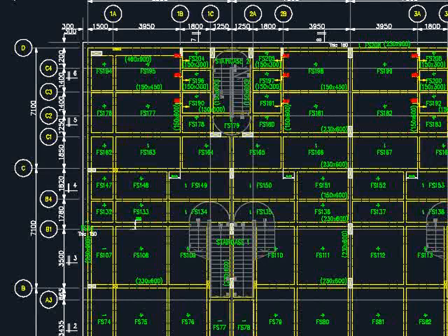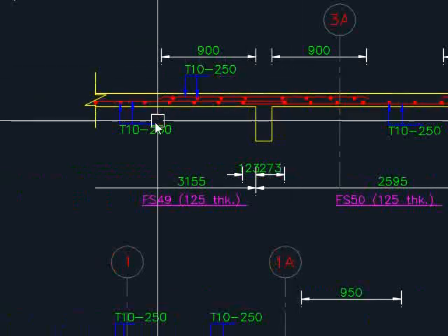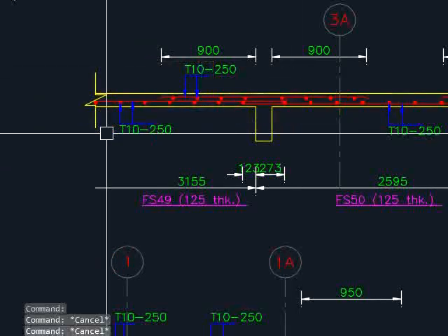There is one more thing that I need to mention about the detailing for the slab. Normally, when you do the cut sections, there will be combinations of horizontal cut sections and vertical cut sections. In the horizontal cut section, let's say, the locations of the main and the secondary reinforcement bar, where the main reinforcement bar, if it is placed in this manner, that means another section which is perpendicular to the section, the reinforcement bar will be at the opposite arrangement.